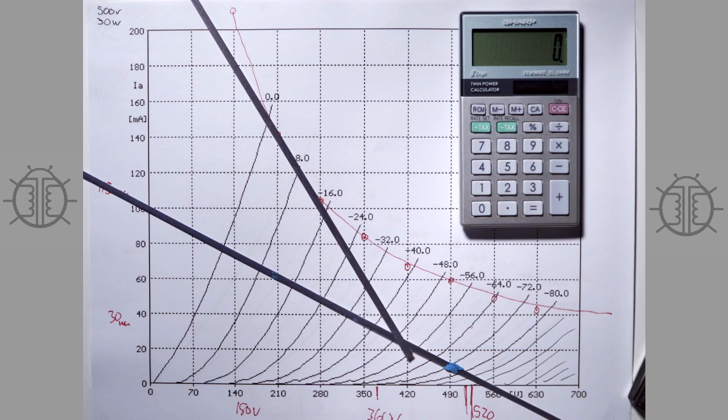And so it's a little bit more tricky, and I haven't found an equation that always 100% gets you there yet. But suffice to say, your goal with a push-pull AB1 output stage is to swing through the most voltage and current that you can. And so if you're trying to maximize power, you're setting your operating point here to swing through the most voltage and current that you can to get the maximum output power.